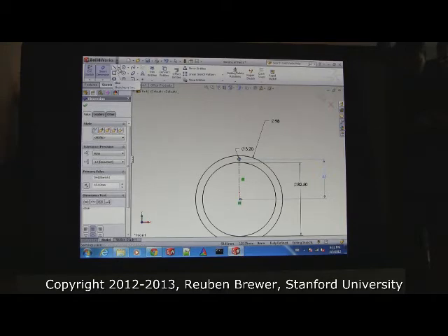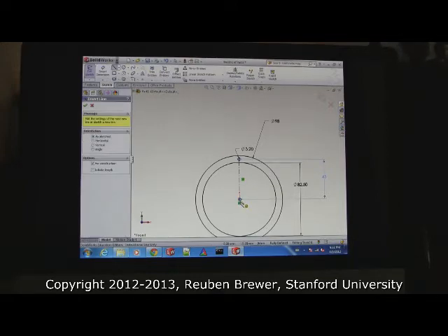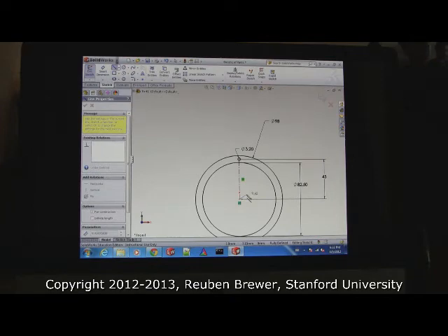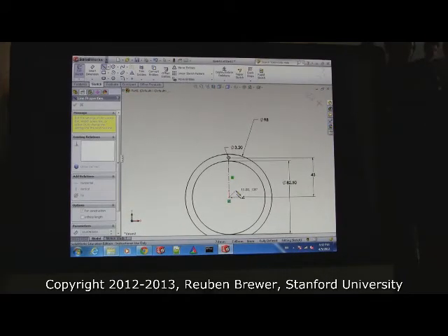That means we have to set an additional dimension, that being the angle. So go ahead and take another center line, put one end at the center. It's asking if I want to make it dimension driven. Say no. Oh, yeah, okay. Do you have that? So what happens here is... That's right. Okay, so you're snapping the wrong. Delete that circle. And then when you put it in again, zoom in so it doesn't snap.